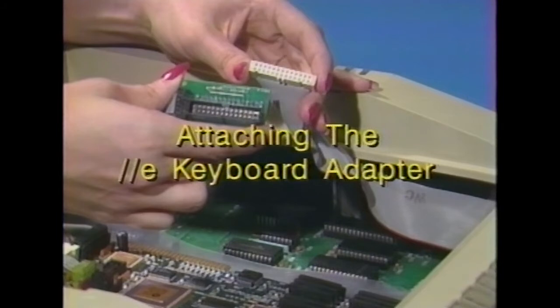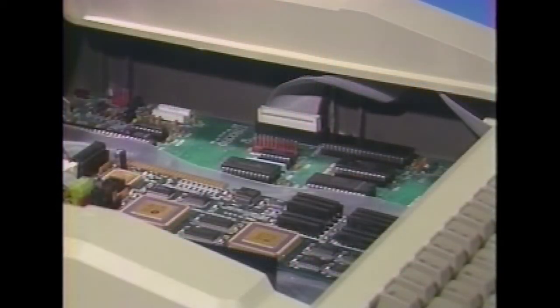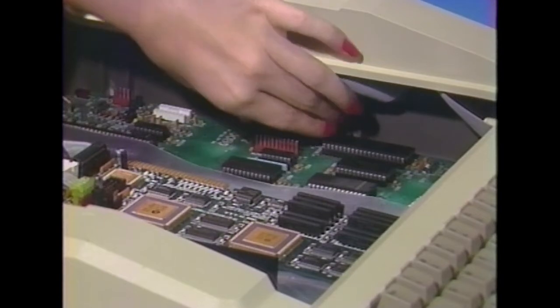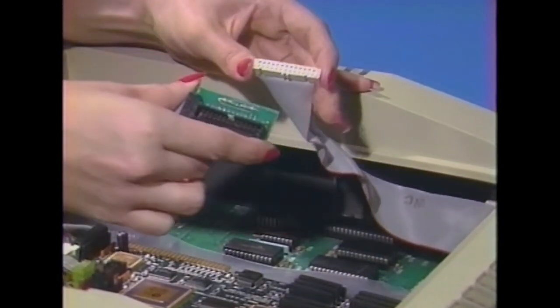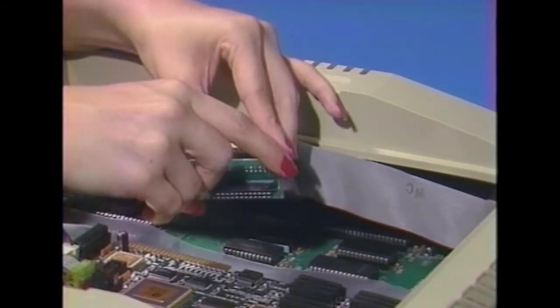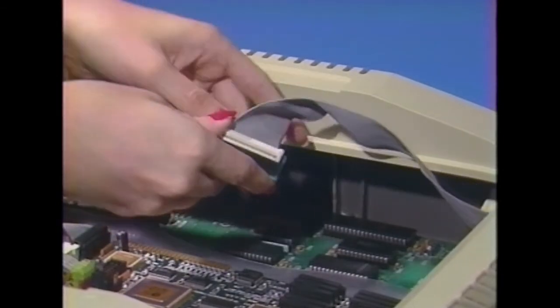Attaching the IIe keyboard adapter. 2+ owners may fast forward to the next section. If you want to use the IIe's keyboard with the PC transporter, locate the IIe's keyboard cable connector. It is located on the far right side of the IIe motherboard. Disconnect the IIe's keyboard cable connector from the Apple's motherboard. Now locate the IIe keyboard adapter card. It looks like this. Attach the IIe's female keyboard connector to the male connector on the adapter card.